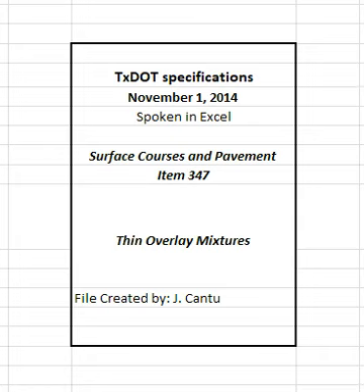4.6 Hauling operations. Clean all truck beds before use to ensure that mixture is not contaminated. Use a release agent shown on the department's MPL to coat the inside bed of the truck when necessary. Use equipment for hauling as defined in Section 347.4.7.3.3, Hauling equipment. Use other hauling equipment only when allowed.